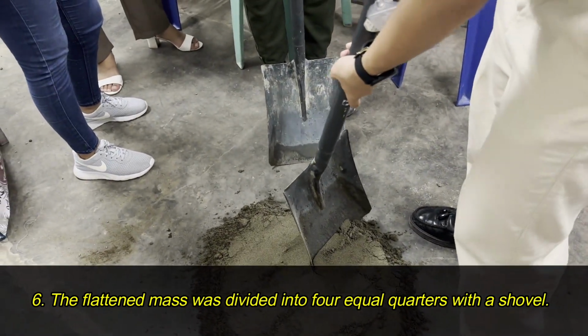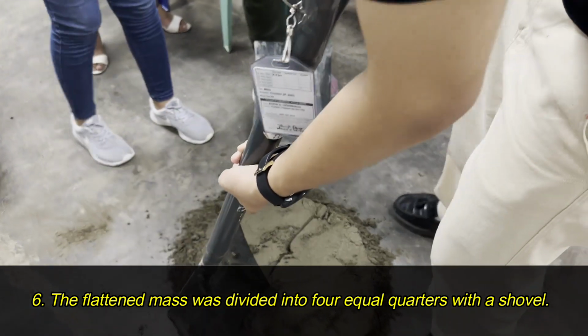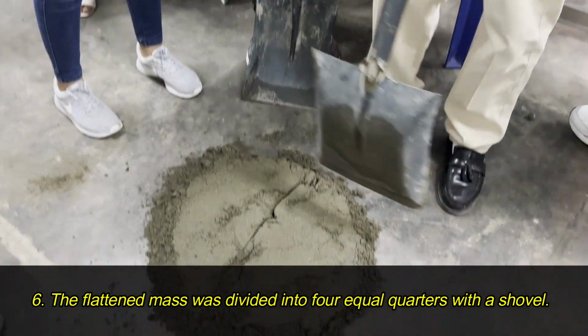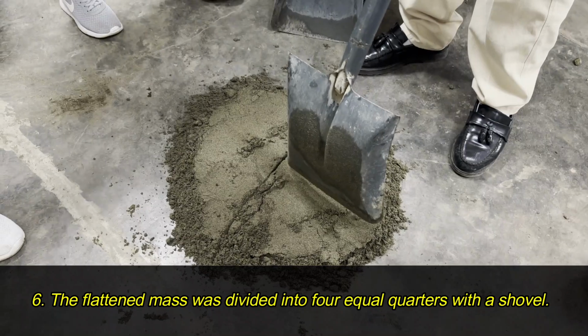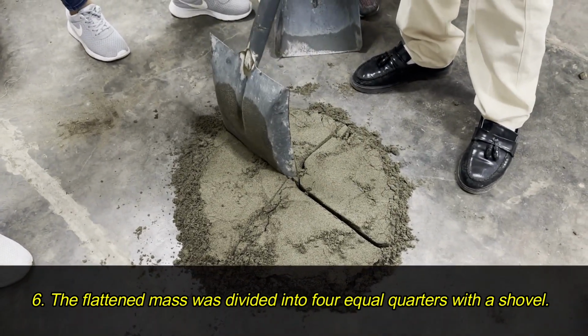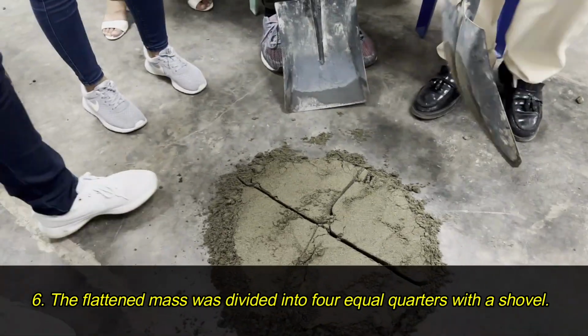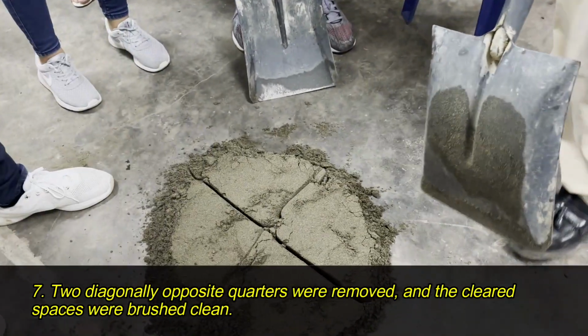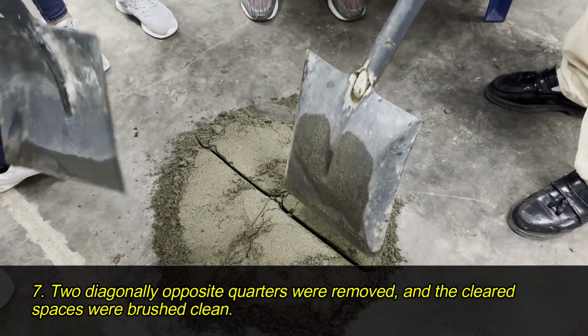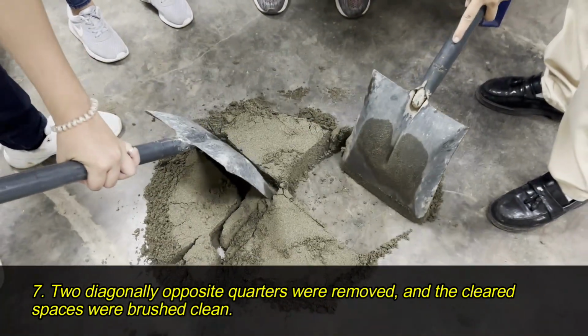Sixth, the flattened mass was divided into 4 equal quarters with a shovel. Seventh, 2 diagonally opposite quarters were removed, and the cleared spaces were brushed clean.